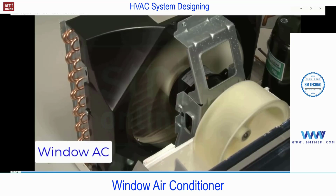And this spraying of the water on the condenser coil, you'll not find in all the models. In some models you'll find it. This will help to increase the efficiency. The same condensed water is going to be available in the drain tray at the bottom, so it can be utilized to cool the condenser to increase the efficiency, but not in all the models.